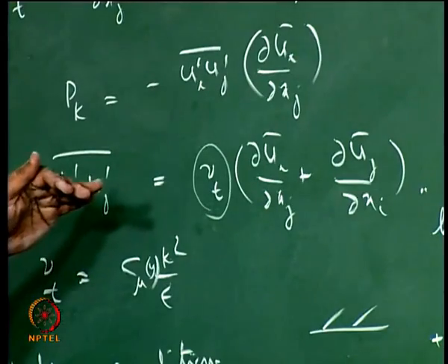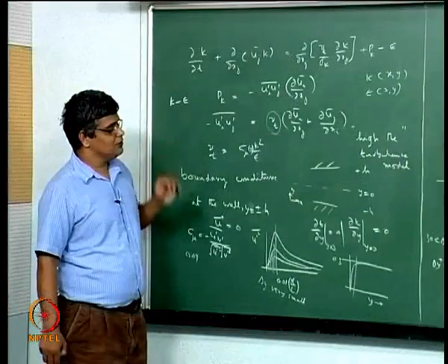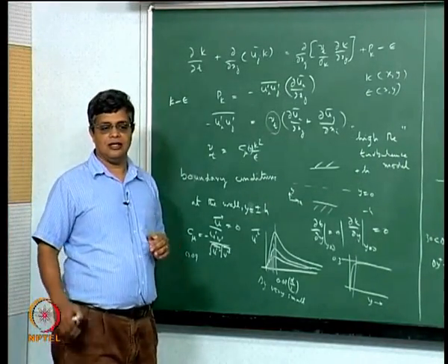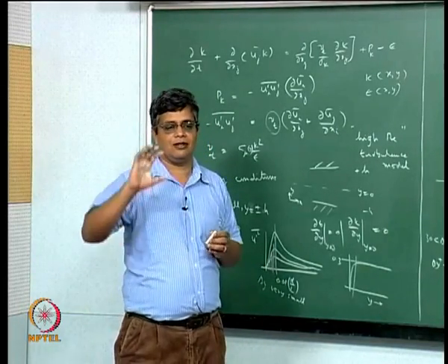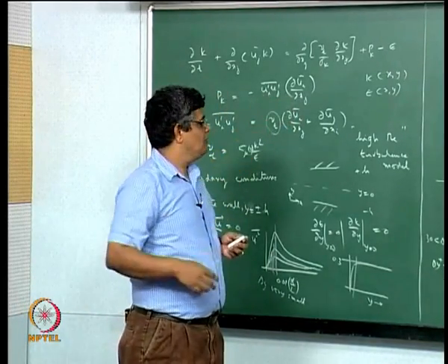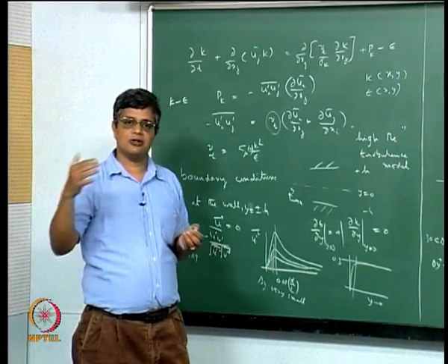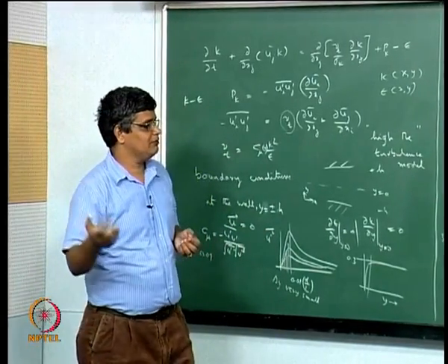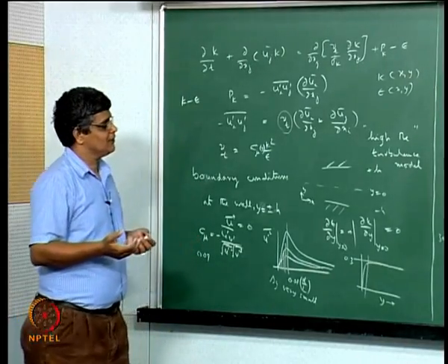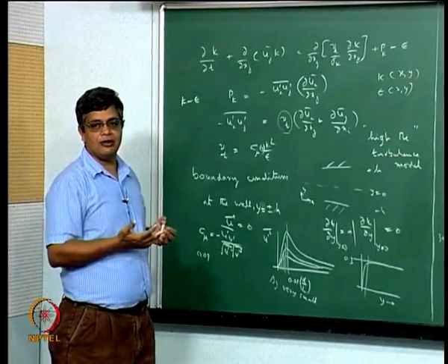So this isotropic viscosity is known to be not so good when you are considering, for example, a swirling flow, or a flow with a strong curvature where you have flow going and then turning, so you have flow in a bend or flow in a coil tube, or flows with strong buoyancy.